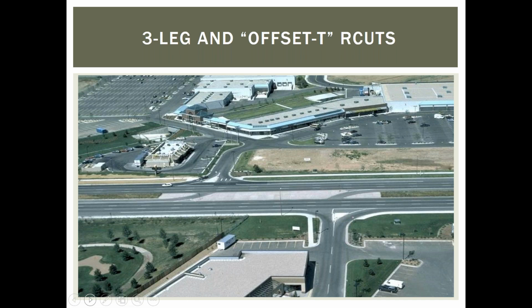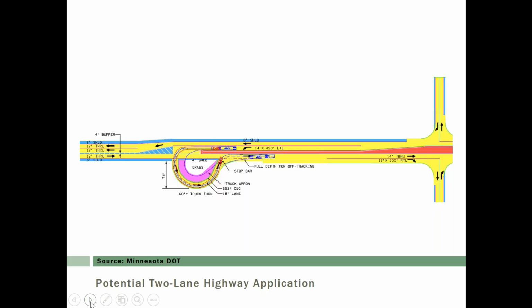And I know a lot of projects that we've done in the past have tried to line up these offset approaches at intersections. We reconstruct the alignment to bring the two together. Well, if you've got an existing scenario where you've got two offset intersections like this, the restricted crossing U-turn option may be very good, as opposed to reconstructing the alignment on one of the approaches, trying to bring them together into one intersection. There are actually advantages to the offset variety.